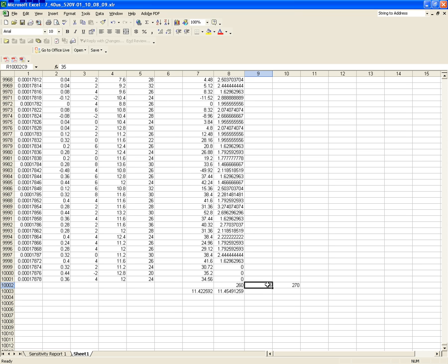Basically I'm saying that the current is lagging the voltage by 35 degrees here. And that, with a 260 ohm inductive impedance plus the 10 ohms resistance, gives me an output power on the average of very close to what the battery power is.